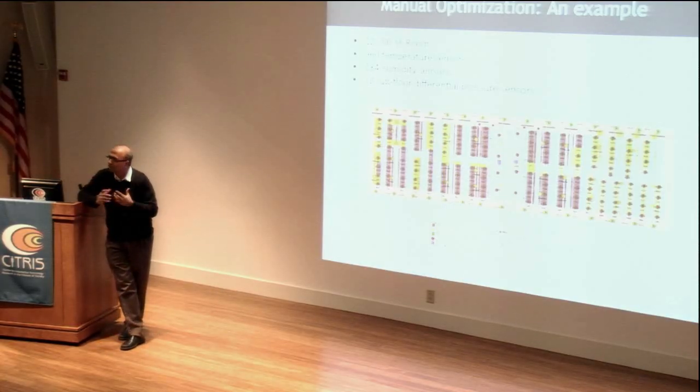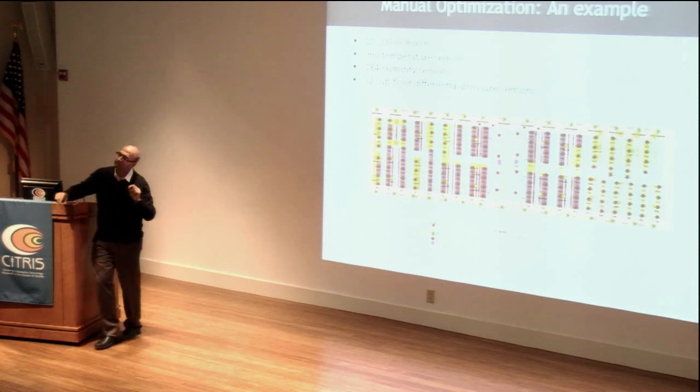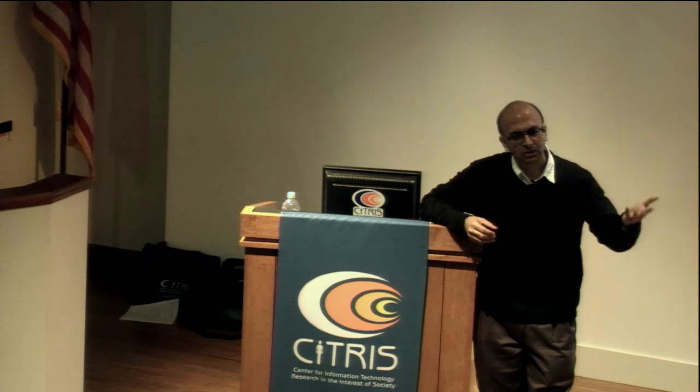So as part of the process, we will first understand how much volume of air you need. We'll calculate what temperature you need. Those things can be calculated pretty straightforwardly. After you have understood that, you go through each row and look at what kind of load you have in each row. Now, this is the place where the lack of information starts to hurt you. If you knew how much load you have in each particular rack, if you could control the volume of the air that goes into each of the rows, it'd be much easier to do this task. But you don't have that information.